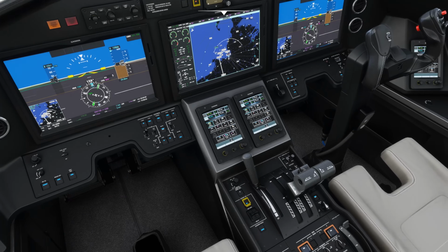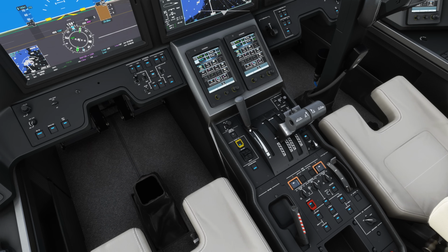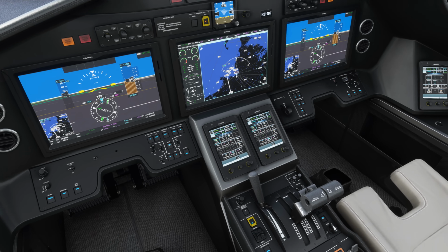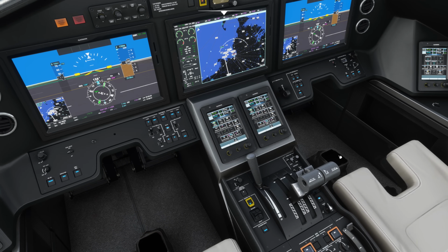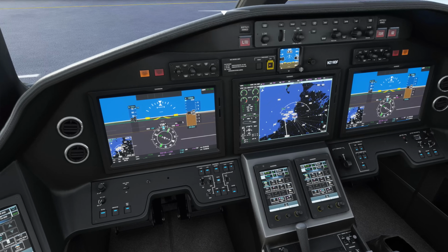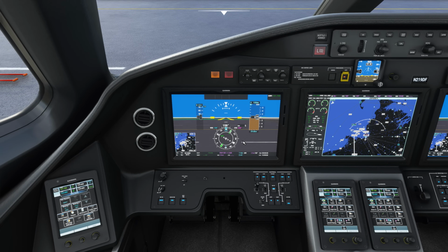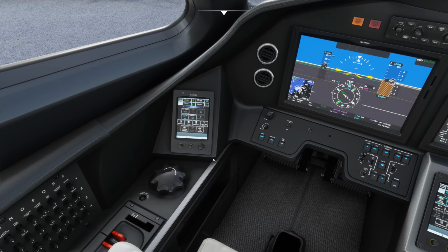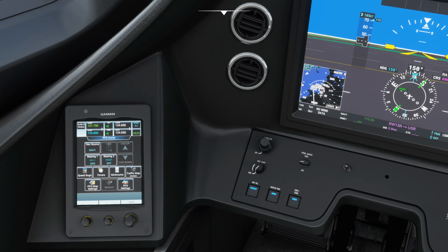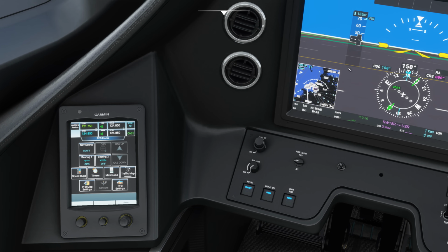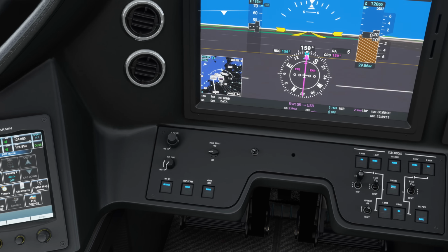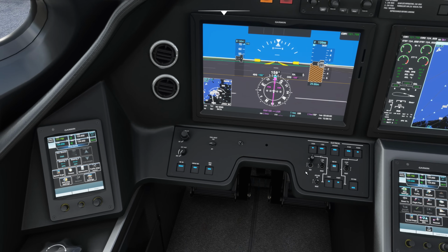At this point, once again, verify flight controls are free and clear. Speed brakes are retracted. Flight instruments and avionics are set. We have altitude set, initial heading set, flight speed set. We need to change the CDI over to the FMS. So we're going to come down here to the pilot touchscreen for the PFD, go to nav source and change it to FMS. Now aligned with the autopilot system for flight.